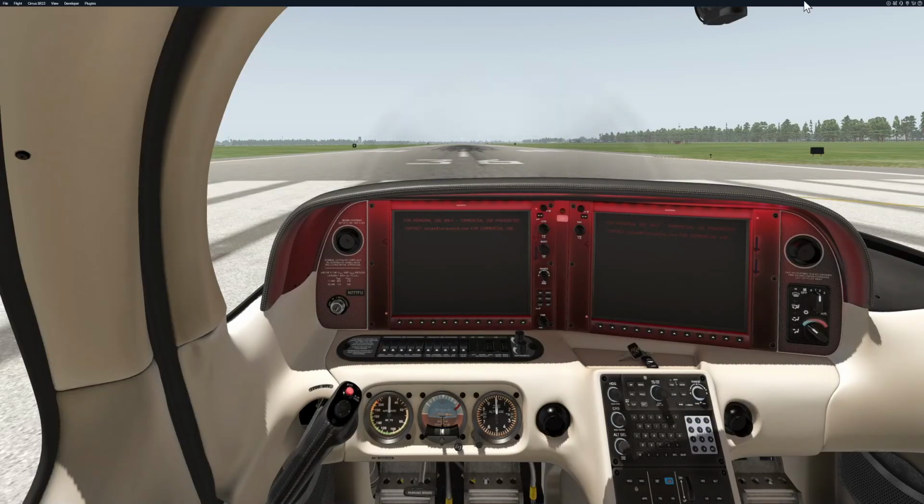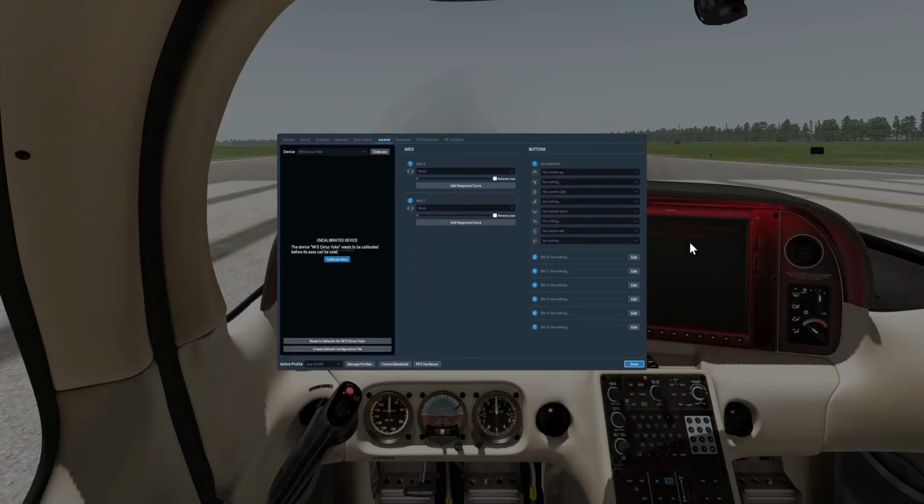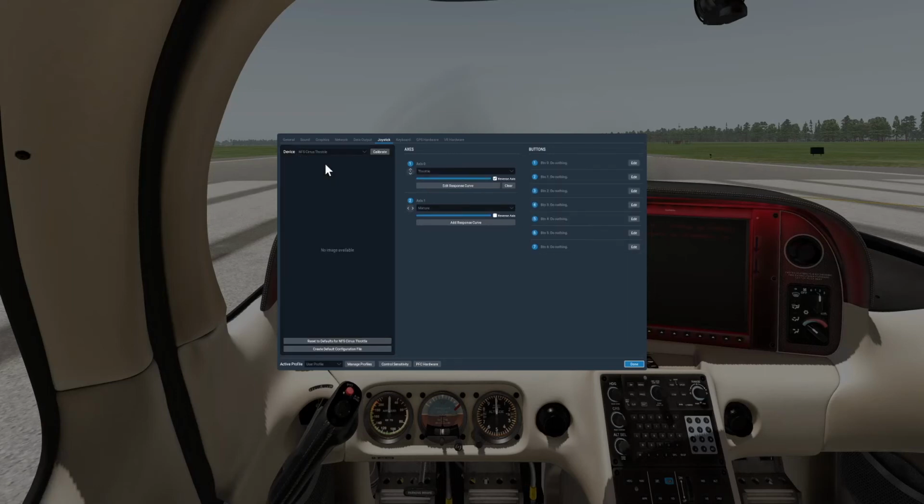So once you have the aircraft loaded, you're going to go to the settings, and again you're going to find the Cirrus Throttle. Now we've already set the throttle in the mixture. Button number 1 is the takeoff go around button. Okay, so again, that's set within the NFS Cirrus, the NFS G1000 software, so it's not set within XPlane.